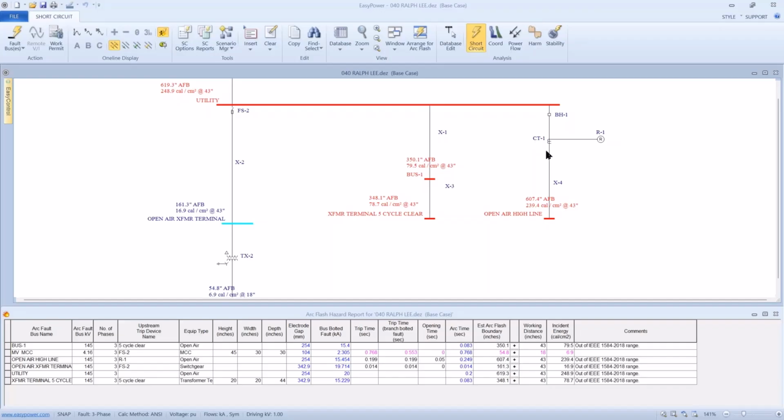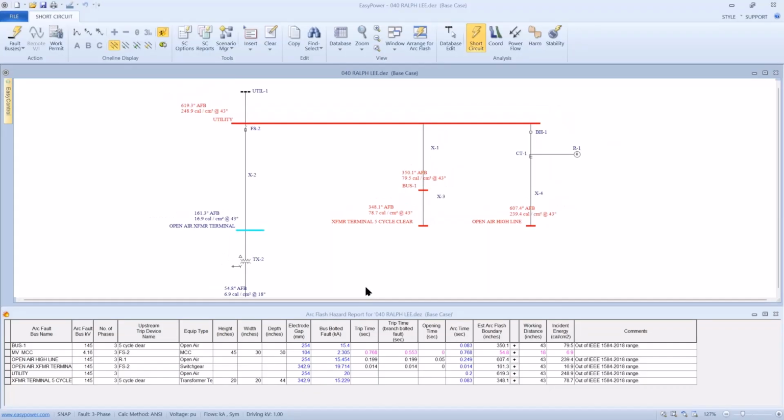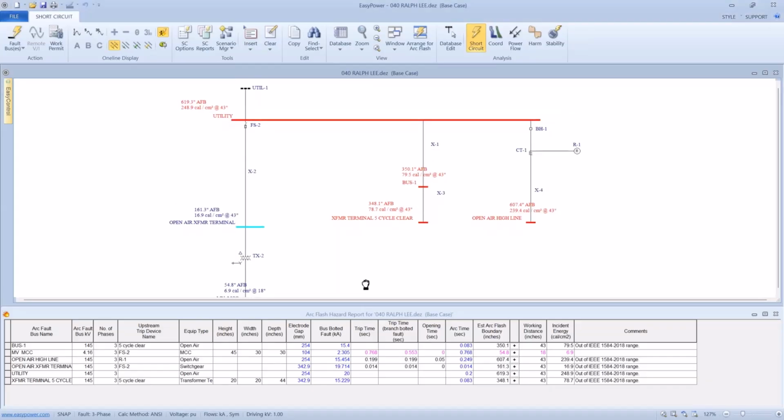That's a good question, and the answer is yes. Down here, when we have a dark entry, a dark parameter, that means it's using 100% arcing current to make this calculation. When it's magenta colored, that means it's using reduced arcing current as per the standard 1584 recommendation. Because it's now part of the model, it tells us that 100% versus some reduced value is being compared.